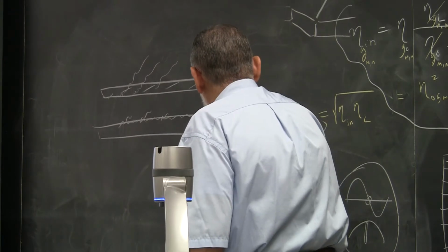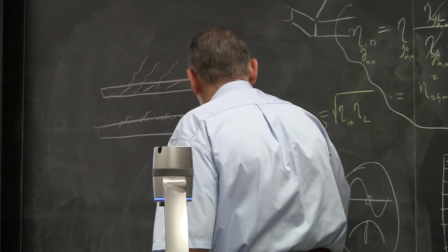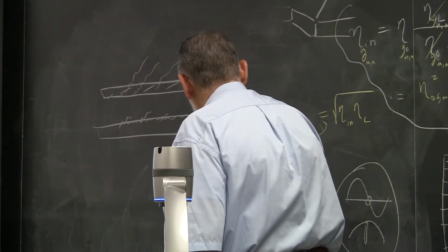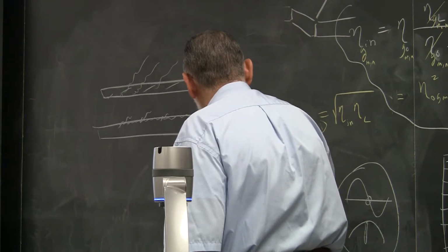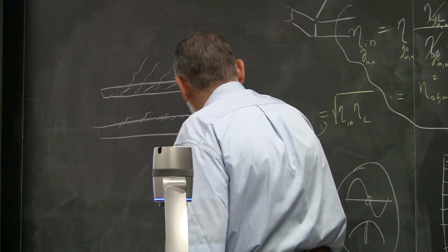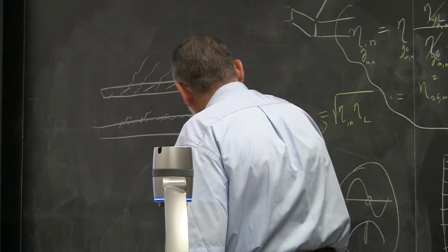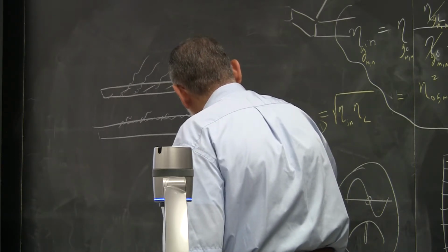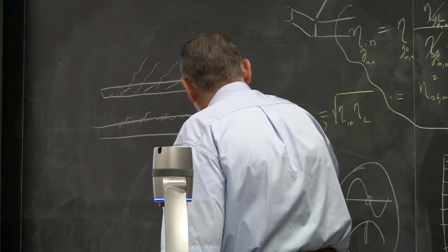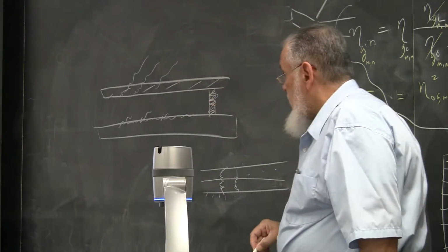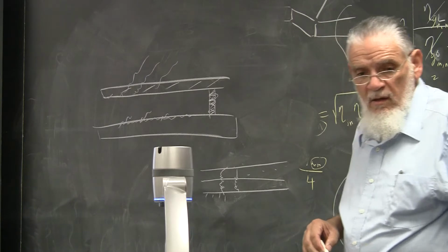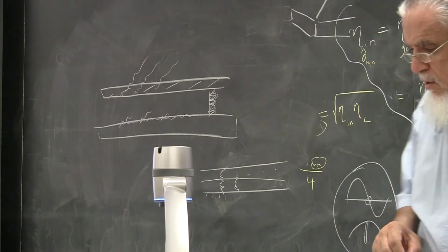So if you imagine your transmission line now, and this one here is grounded everywhere, but this one here is not grounded. The center conductor is right there. This one here doesn't connect to that directly. It connects to that through resistance and inductance, and they are placed every so often. So they obviously are going to cause problems.